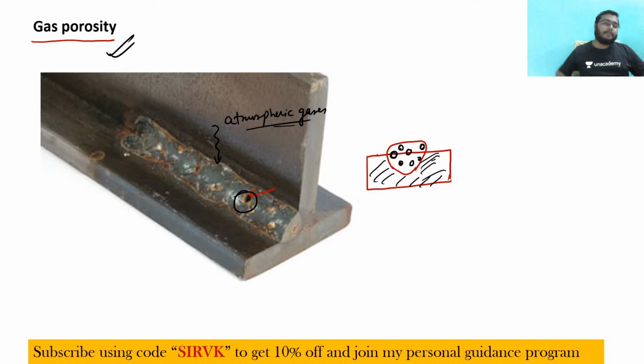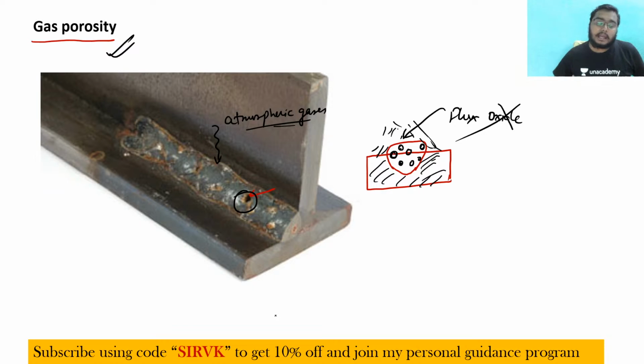Why? Because the entire area will be shielded. If you are using a flux, then the oxide layer will not form, and you will get a very nice, neat and clean weld. And the atmospheric gases that earlier were entering the liquid metal will now not enter. So I hope you understood these kinds of defects.